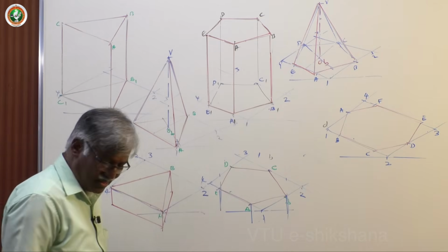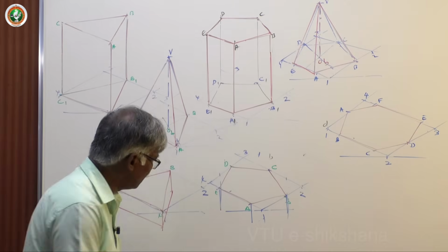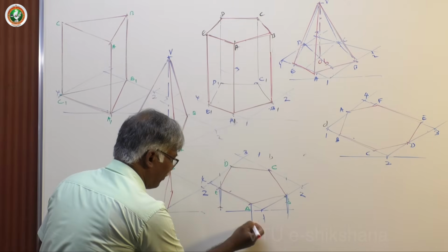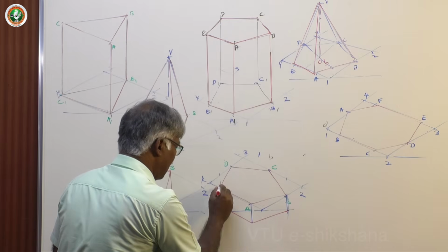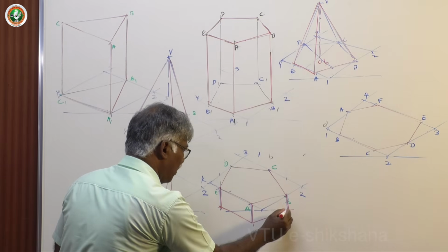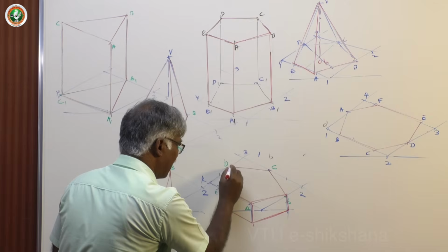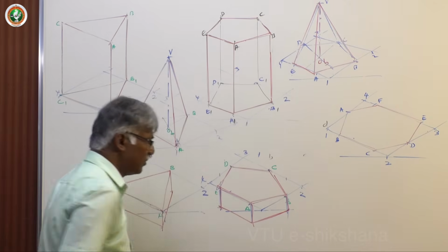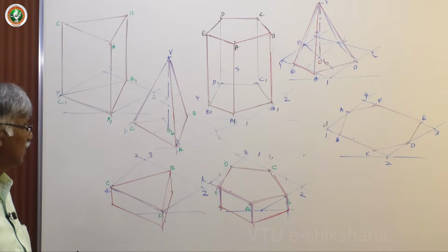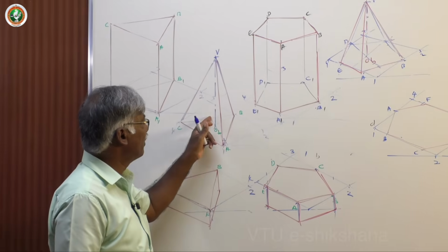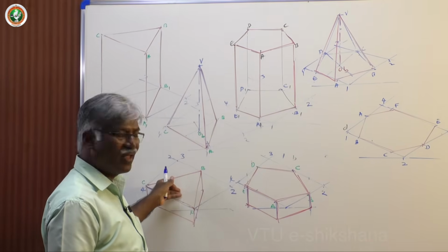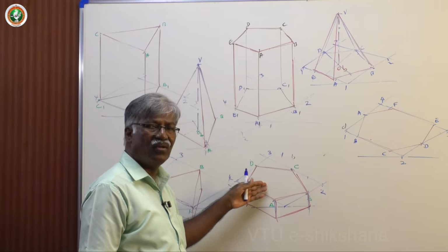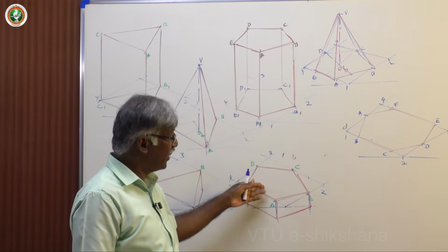Now fix these distances. Say 15 mm or 20 mm throughout. Only 3 lines. Then join them. Dark line. So this is how you get isometric projection of block. So prism, pyramid, block for a triangular, and this is here for the pentagon.